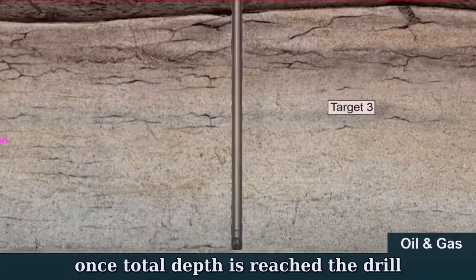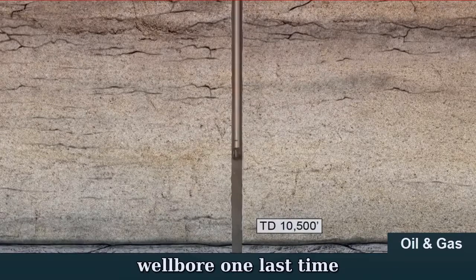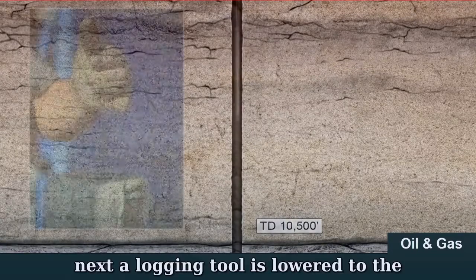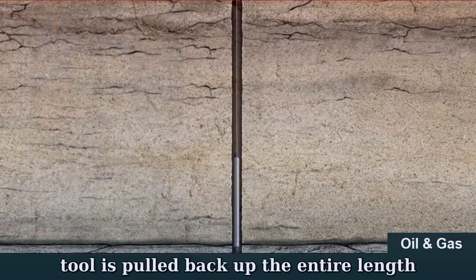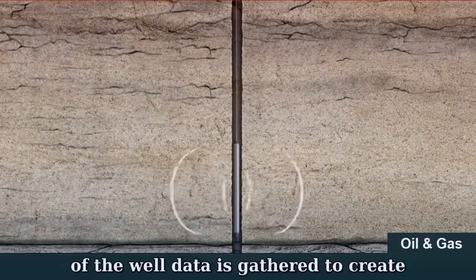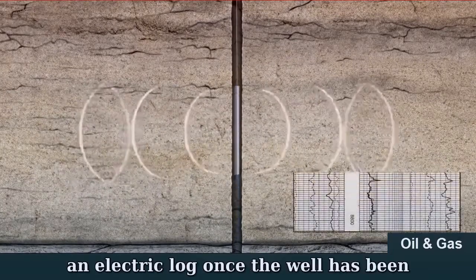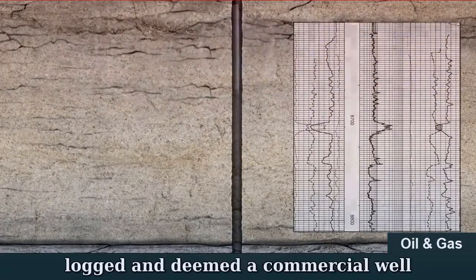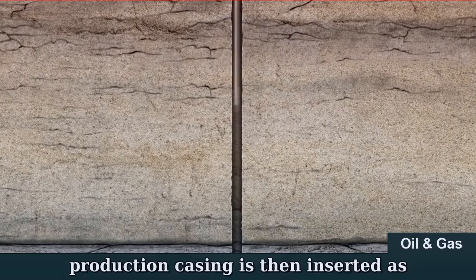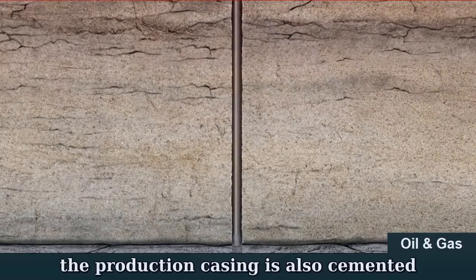Once total depth is reached, the drill pipe and bit are removed from the wellbore one last time. Next, a logging tool is lowered to the bottom of the well on a wire line. As the tool is pulled back up the entire length of the well, data is gathered to create an electric log. Once the well has been logged and deemed a commercial well, production casing is then inserted. As with the surface and intermediate casing, the production casing is also cemented into the hole.